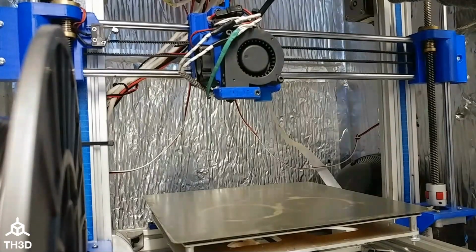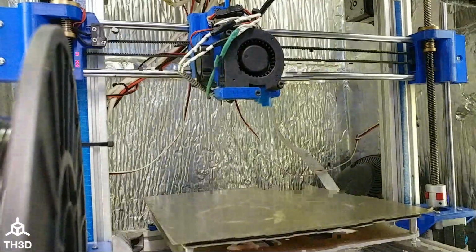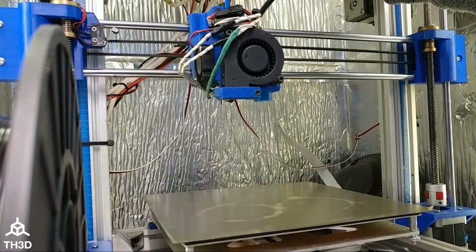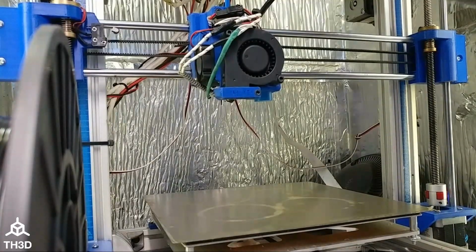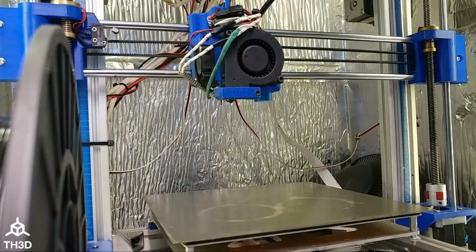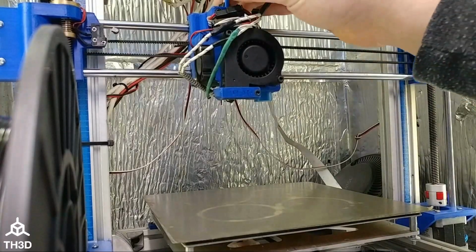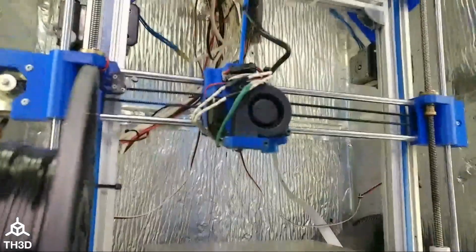But I'm going to tell it to preheat the hot end, and what I'm going to do is move around the cabling and see if I notice anything, you know, sparking, or if I move it to a certain side, it then stops heating. I'm going to turn the bed off because otherwise it's going to get really hot in here. So I'm messing with the LCD right now. And I'm just turning the bed off.